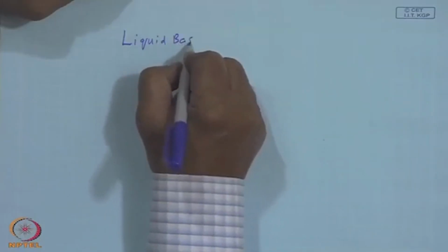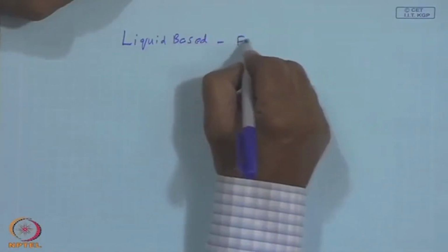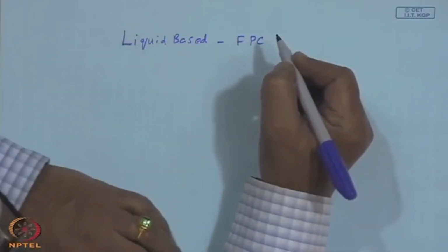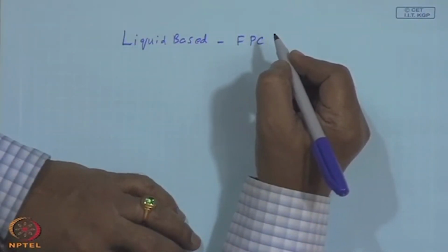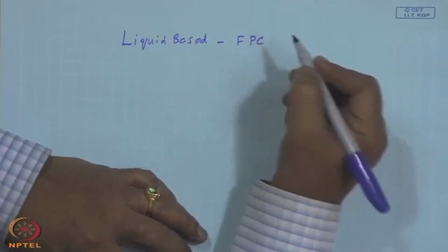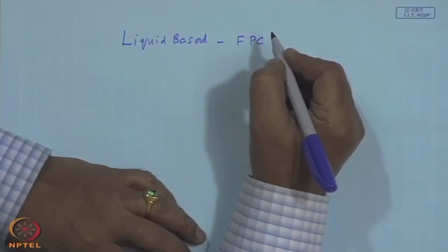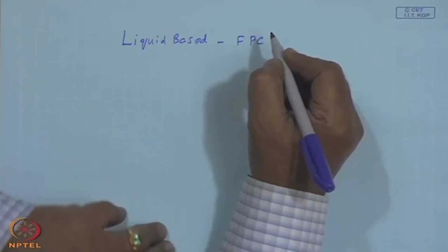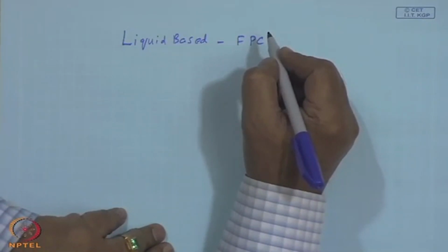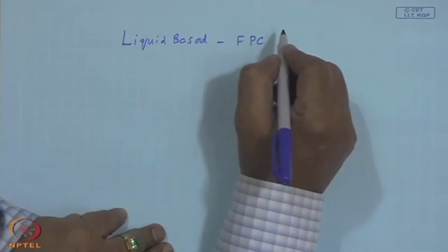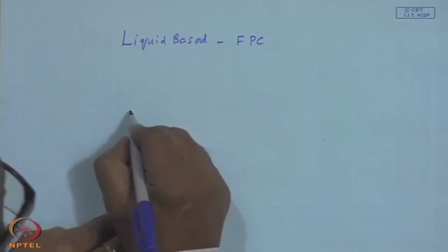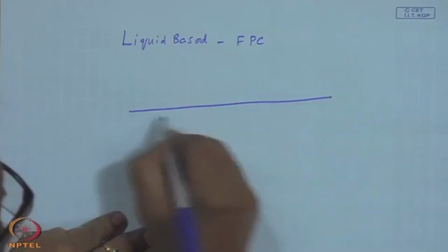Why I said in general liquid based is, it may be water in general, but it could be an antifreeze solution too, to take care of colder climates. We already have gone through the basic collector configuration, the idea being to make the absorption process of solar radiation efficient and with less emission and less convective heat losses, which typically has an absorber plate with